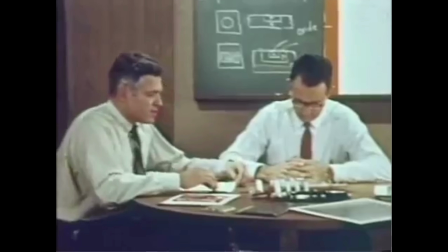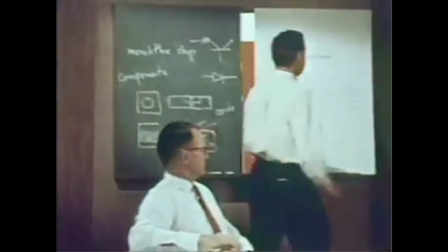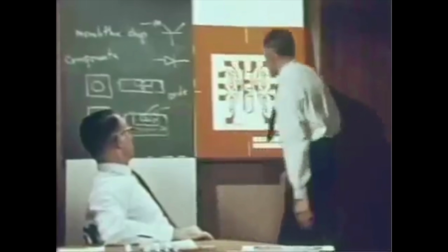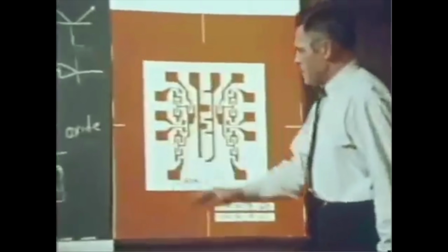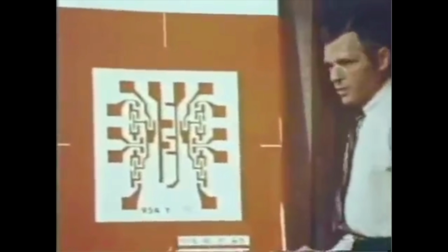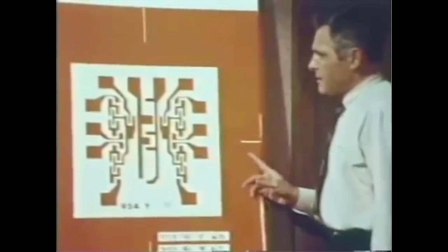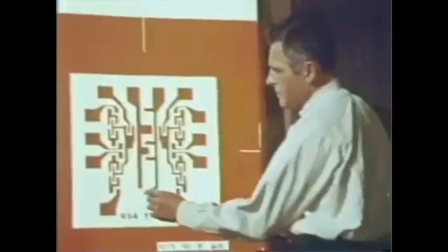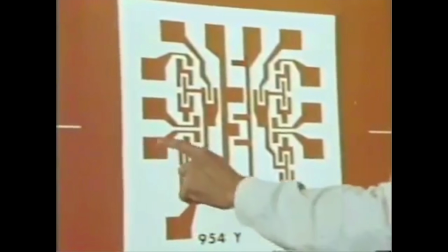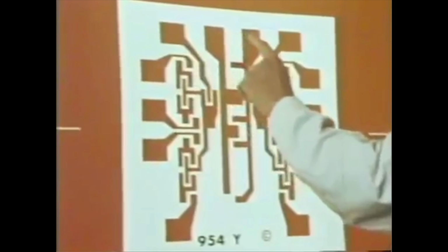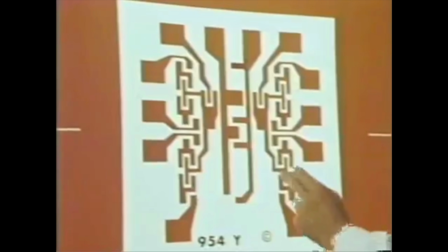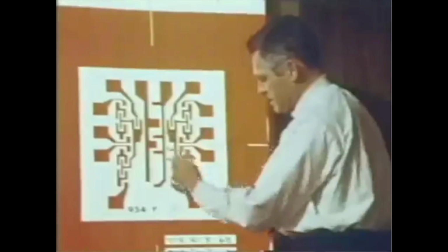Yes, I can. So, we made the engineer pick up a soldering iron. Let's see if we can make an artist out of him by using yet another example. Here is a full-scale 30 by 30 inch piece of typical integrated circuit artwork, which represents in a careful, precise form the interconnection pattern of an integrated circuit. For example, these are the metal pads. These will be on the integrated circuit, the metal pads which connect to the outside world. Here we have the transistors. And here are diodes and more interconnecting metals.